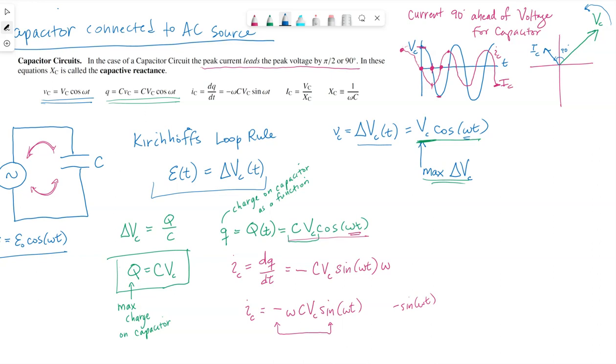This piece here is going to be important, especially when we pull in and attach a resistor and capacitor together. So let's keep that in mind. But let's come back to our equation down here for current, which, by the way, we have up here from the test notes. But I want to talk about this amplitude for a minute. Any number or numbers we have in front of the sine function represents the amplitude, or the maximum, or the peak value of whatever this function is describing.